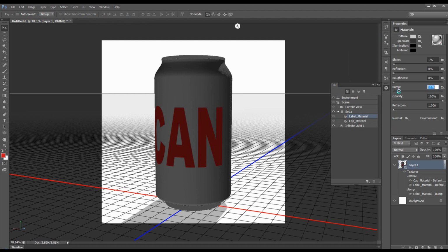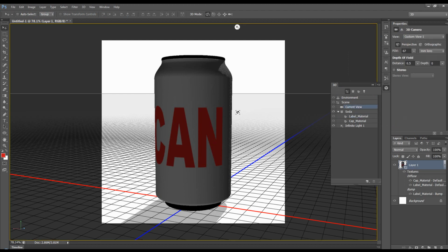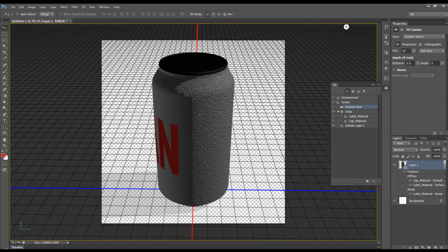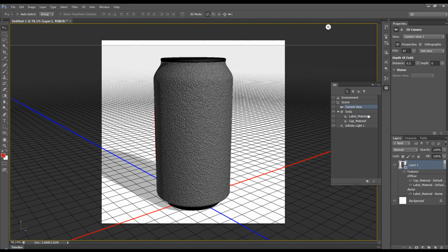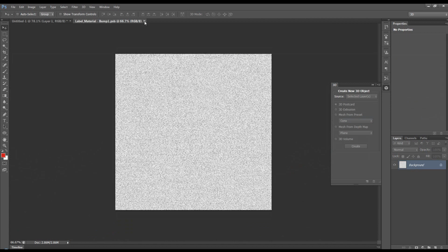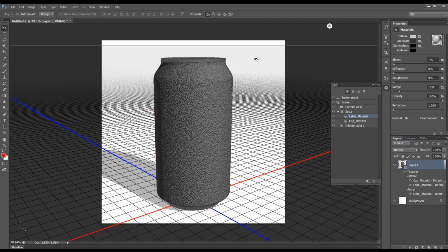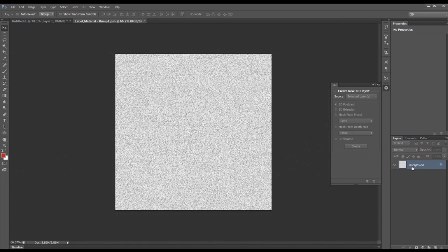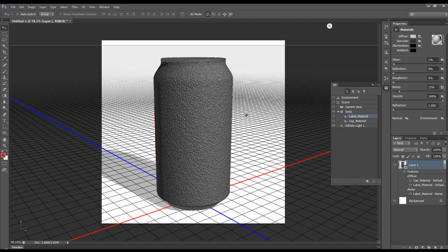click OK, close it, save it, and then turn the bump up, and now you will see that it's got texture to it based on the bump map, which is the document we created here. One tip when you're creating these bump maps, reflection maps, is to create them with smart filters or as a smart object, so they're easily changeable, not like I've done here for demonstration purposes.